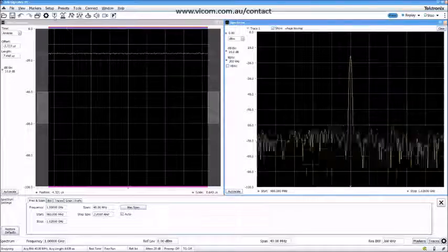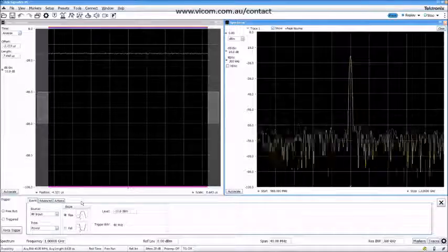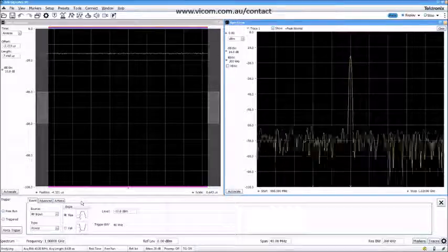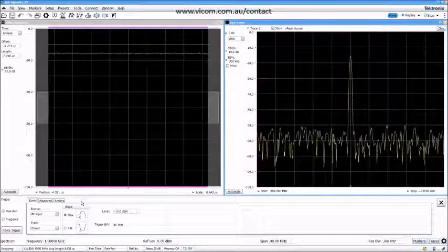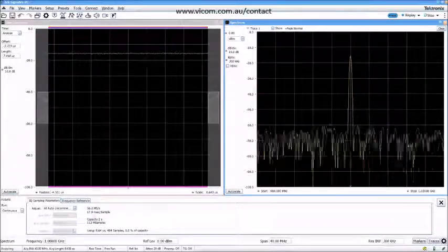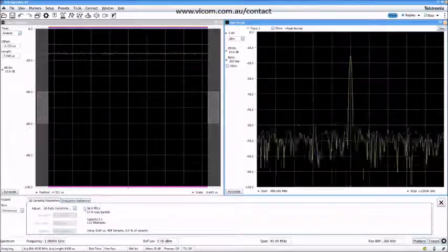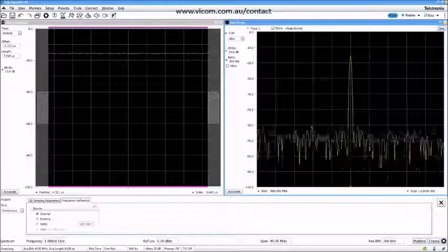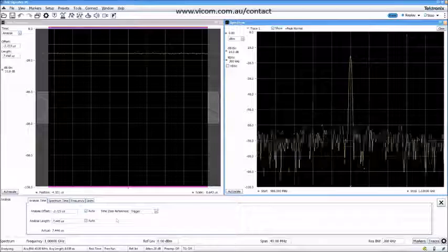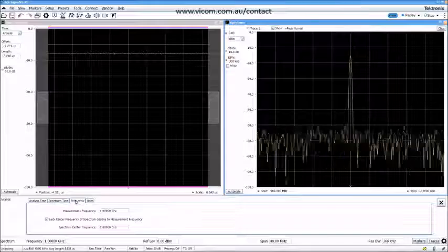The Trigger button gives you control of the hardware trigger for your spectrum analyzer. This allows you to set a signal condition upon which you want the analyzer to capture data. There are many trigger types and options depending on which instrument you are using. The Acquisition Control panel gives you visibility and control of the hardware acquisition parameters like acquisition bandwidth, IQ sample rate, and frequency reference source. The Analysis Control panel provides control of acquisition time, frequency analysis options, and amplitude units.